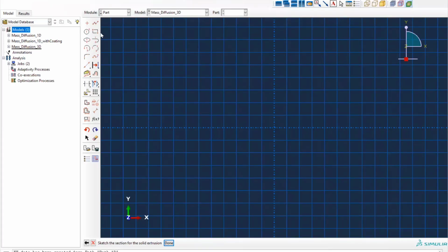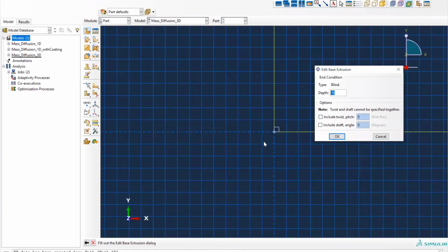And we have extrusion here, so we will set the rectangle 0, 0, and this one should be 38.1, and the height should be 38.1, and then the extrusion should be 12.7, half an inch, I guess. And okay.